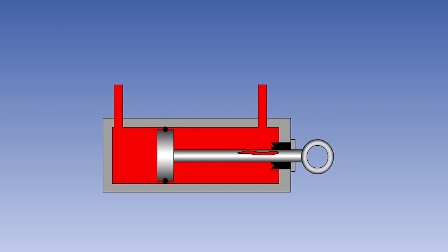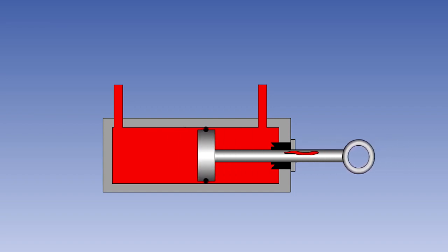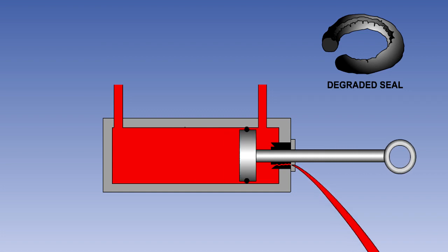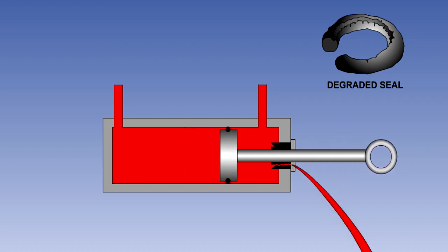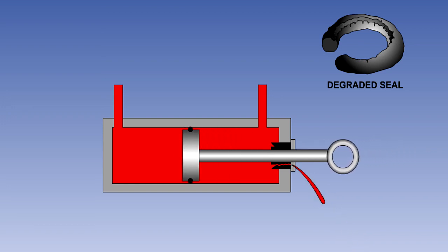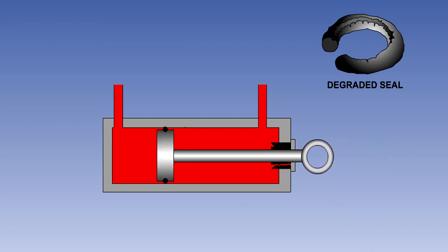Dynamic seals require lubrication to remain effective, and wetting of the bearing surface, or a slight seepage from the seals, is normally acceptable. Seals are made in a variety of materials, depending on the type of fluid with which they are to be used. If a seal of an incorrect material is used in a system, the sealing quality will be seriously degraded, and this may lead to failure of the component. Similarly, if the incorrect hydraulic fluid is used, it will almost certainly damage the seals.